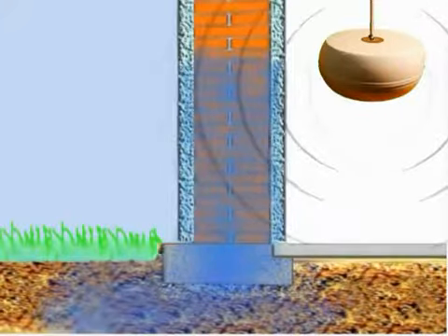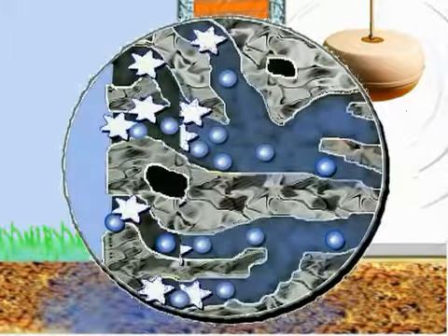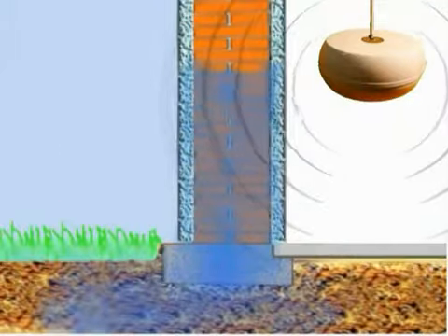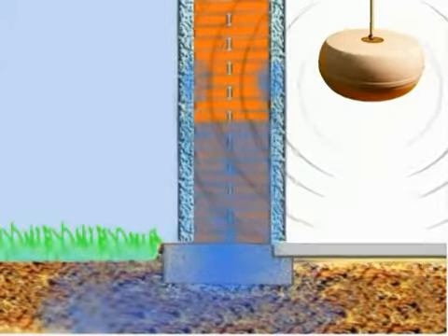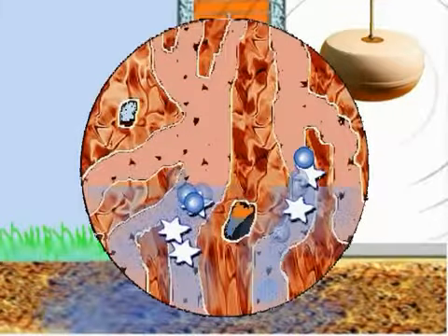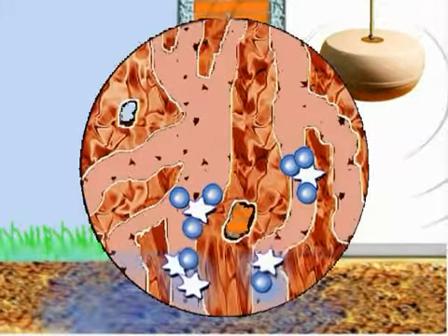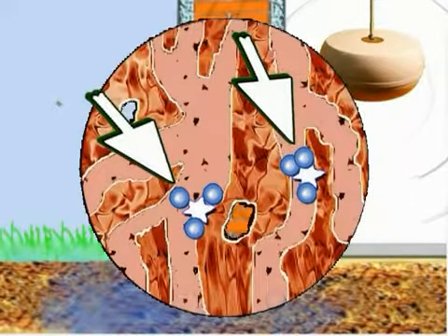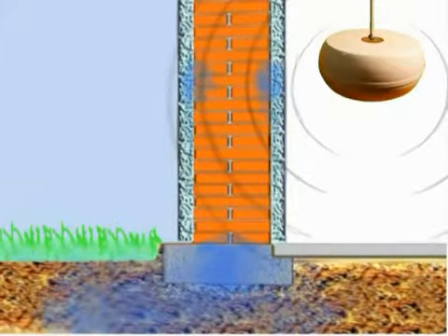The fewer salts there are in the basic structure of the building, the less residual moisture is in the wall. However, the large part of the masonry moisture moves back into the ground through the capillary system in the wall, which is the actual phase of dehumidification. What remains is the chemically bound residual moisture in masonry.